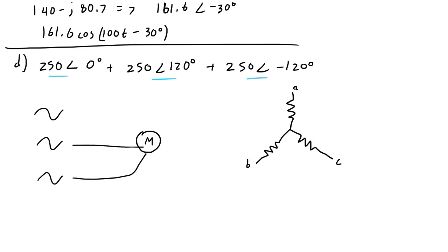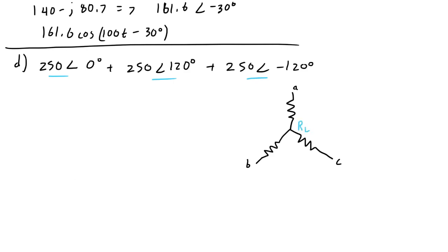and they are in such a way that they are spaced 120 degrees apart from one another, then you don't need a return path for the current. You can just get away with connecting your load right here, to 3 wires. So you save a bunch of money on cabling, and all it really took was a phase shift. So that's the magic of 3-phase power. No return path is needed.